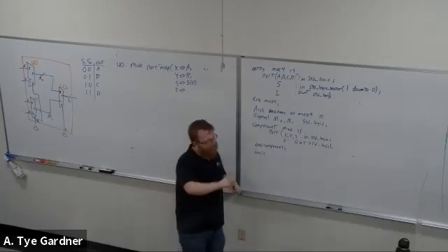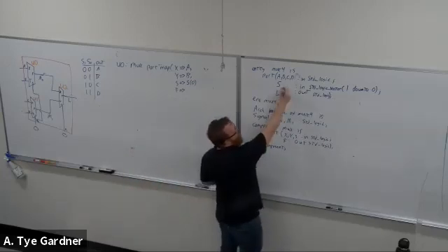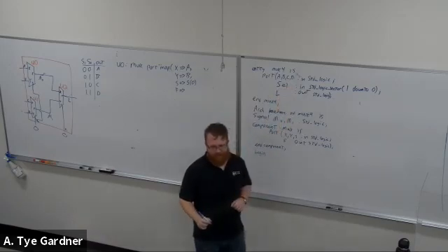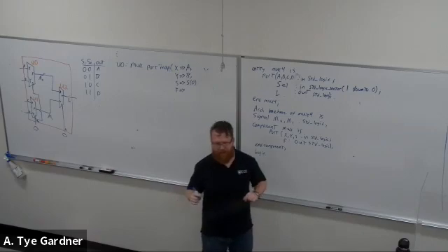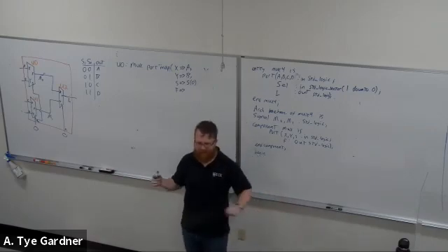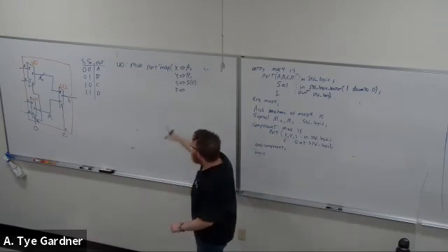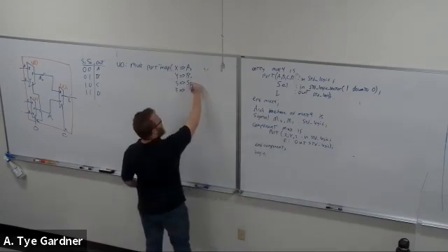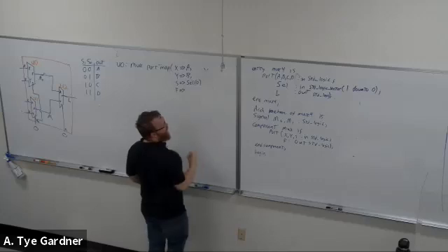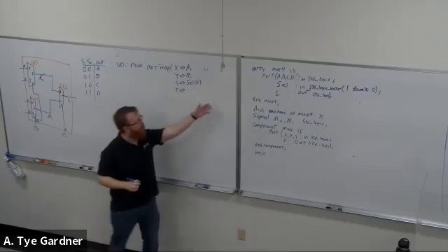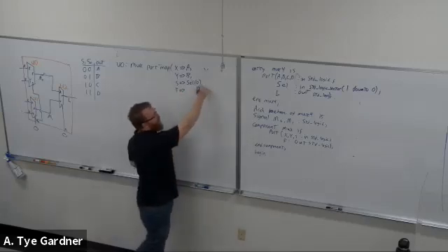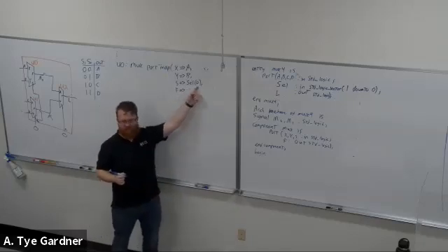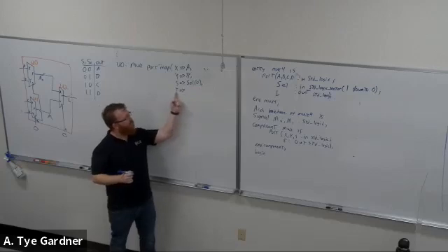Okay, let's go back and rename it. See the space I gave it? SEL. Select turns out to be a reserved word, so SEL for select. Now, when I write this, SEL at 0, right? Because SEL is my 2-bit vector. Now it's getting mapped. That makes sense, right? So this is how we access 1 bit of that select signal.